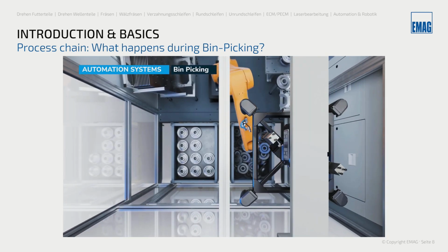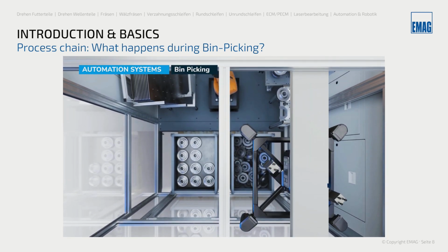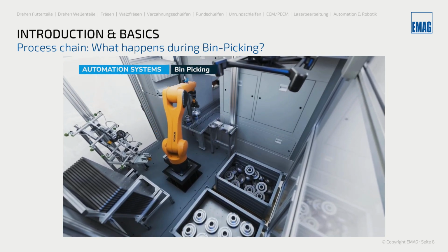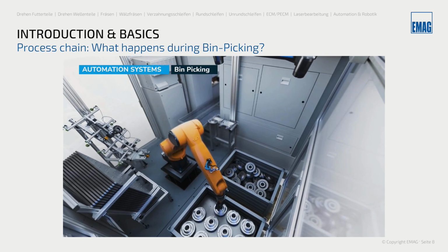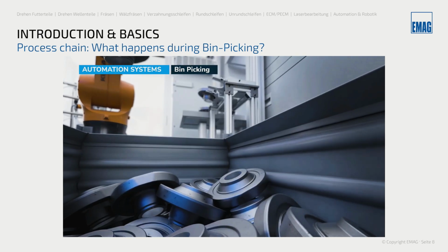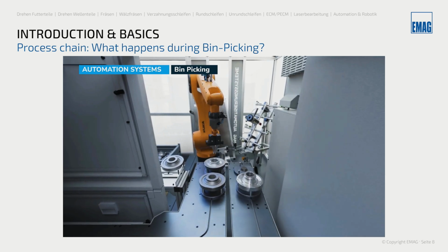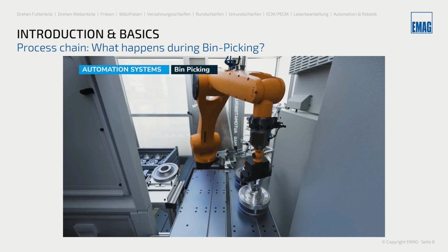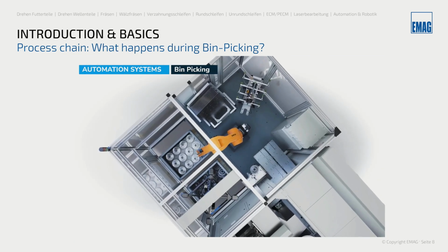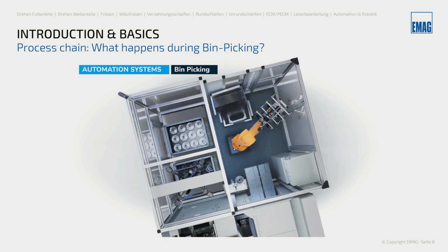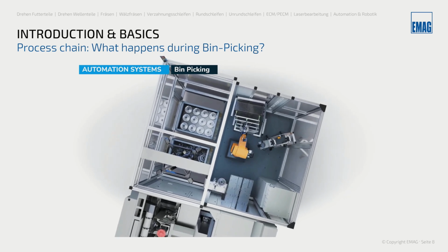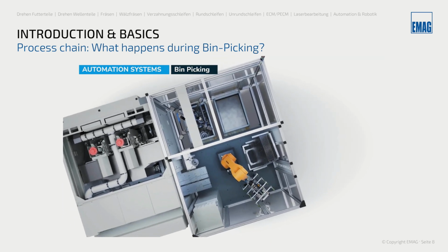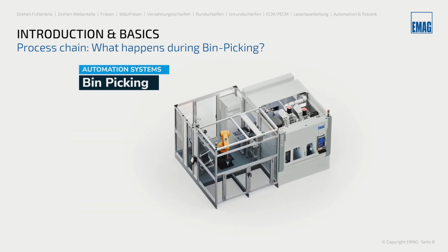the finished material. Now we can see here the robot loads the first position and then takes the finished part from the first operation and loads it to the OP20, because we can obviously work on both sides of the machine. Here we can see again, placing the first raw part, changing the second part and picking up the finished parts into the bin. Now that the first layer is finished, the robot will automatically change the gripper system, pick up a blister so the next layer can be started. Everything of this goes fully automatic.